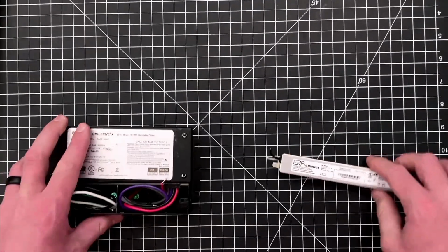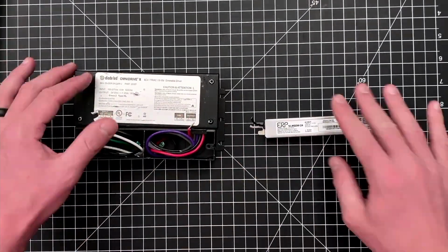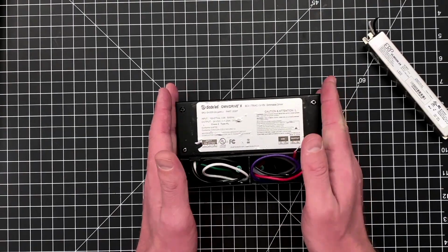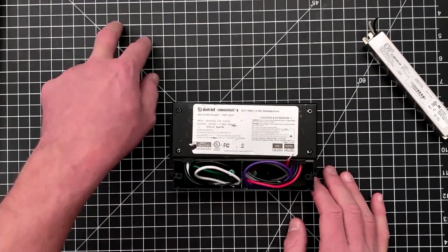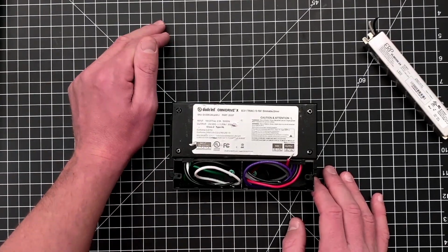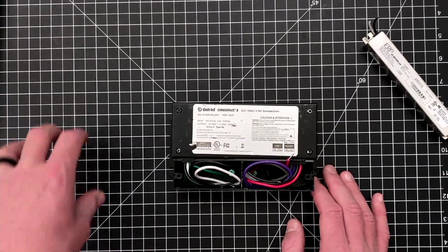As I talk about drivers really quick, I just wanted to mention 2 things on drivers. I'll go back to the top down here. We'll skip the size. There's really 2 drivers I want you to recommend for everything. There's the OmniDrive X, which is our true universal driver, meaning that it can do triac dimming, ELV dimming, and 0 to 10 volt dimming. You can have multiple inputs coming in, so 277 down to 110 in.